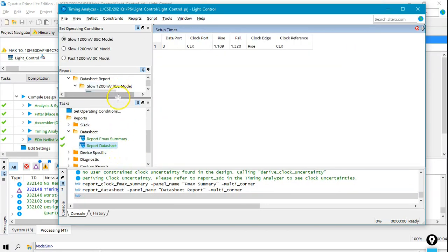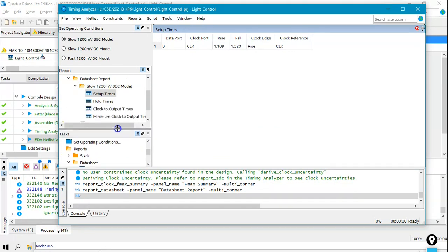So now let's measure, not the setup times, that are fractions of nanoseconds or just very few, or the hold time, but the clock to output time. The clock port is like this. You are changing now the clock from low to high, and the Z takes almost 8 nanoseconds to change.